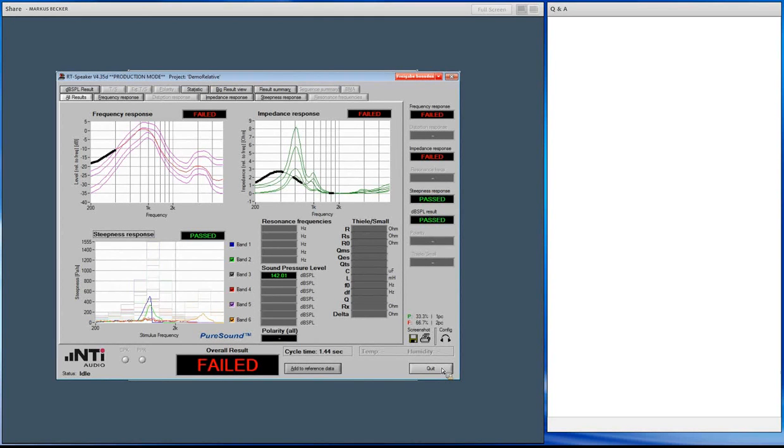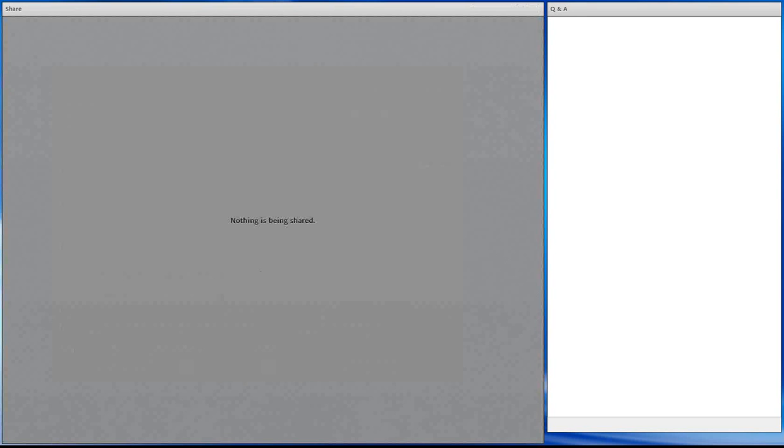The borderline samples, by the way, can be used now to fine-tune these tolerance limits. You can add them to the reference database and recalculate the tolerance limits. So first of all, of course, you must make sure that the borderline sample is acceptable. But if it is, then you can add it to the reference samples, and that will widen, of course, a little bit your tolerance limits, but that will allow you to better identify correctly all good working devices. So let's go back to our presentation.